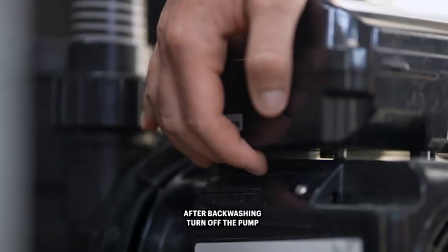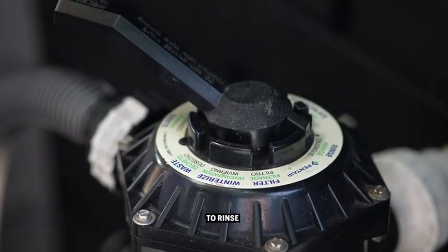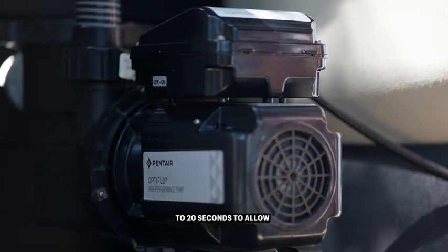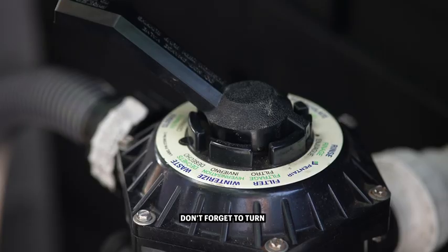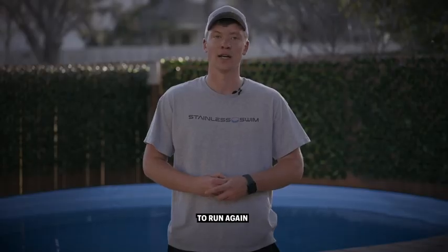After backwashing, turn off the pump and switch the multi-port valve to rinse. Then turn the pump back on and allow it to run for 15 to 20 seconds to allow the filter media to settle. Once you are done with rinsing, don't forget to turn the multi-port valve back to filter and allow the pump to run again.